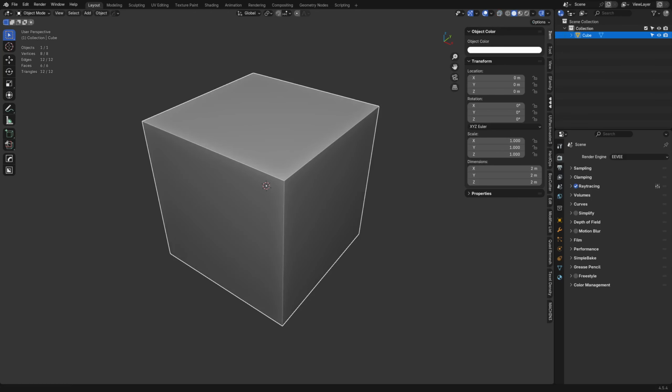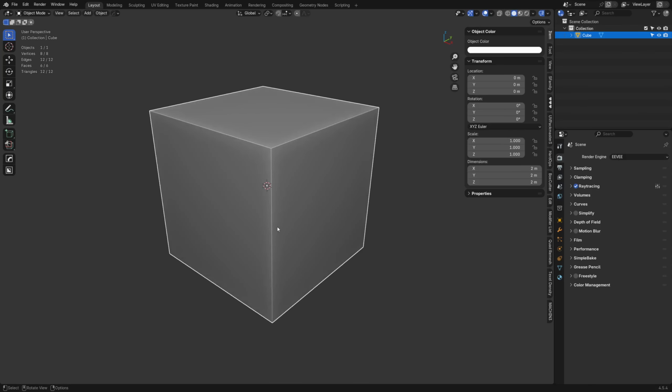And I'll try to explain things as we go through this, but basically we want to work on the desktop first, so we're just going to get the proportions right. We're not doing this with dimensions. You could do that potentially, but for this video, we're just doing proportions. You'll see when I hit tab, it doesn't go into edit mode. It brings up a pie menu. This is the machine tools add-on. You can hit control tab and you'll get a pie menu as well. You can go into edit mode, object mode, or whatever the case.